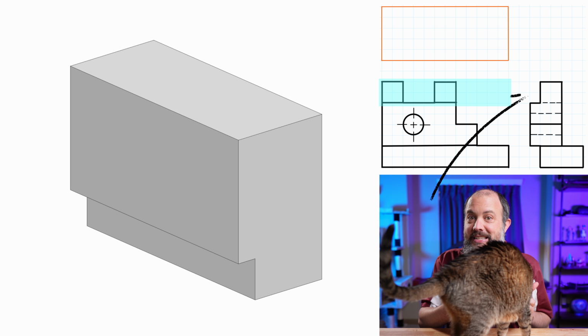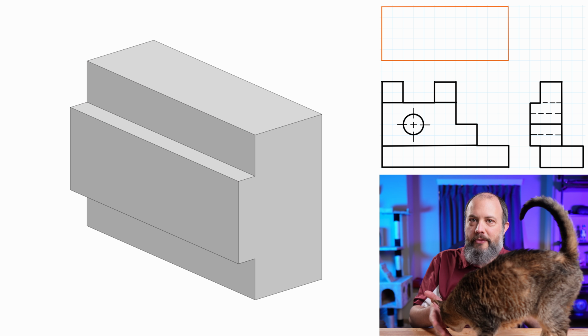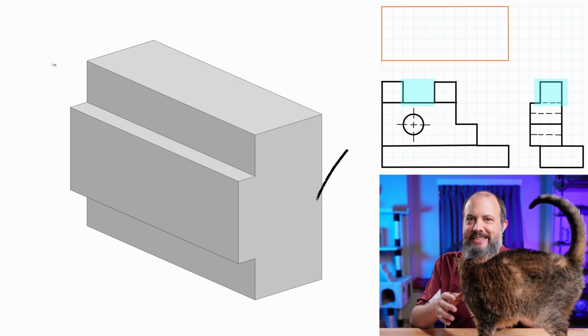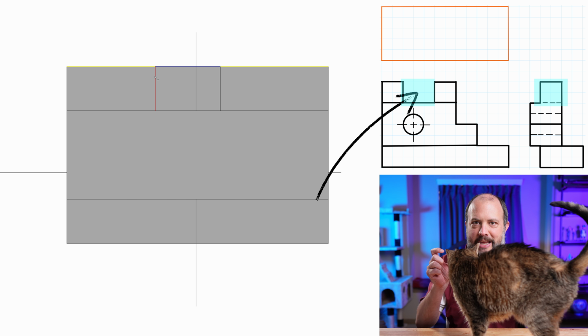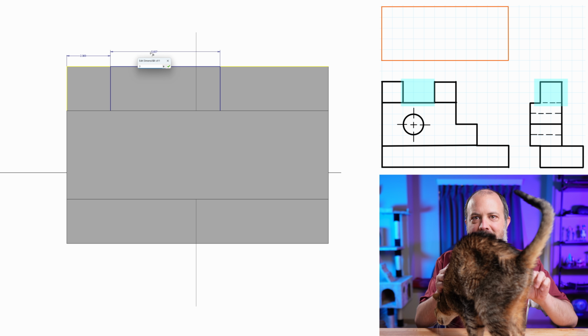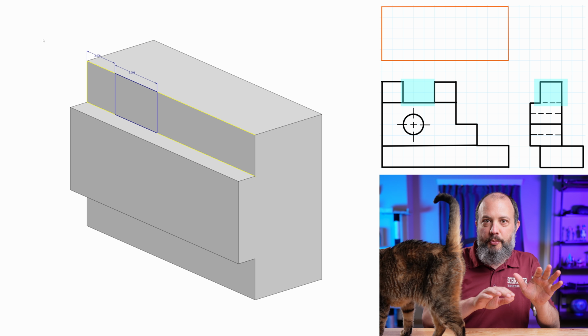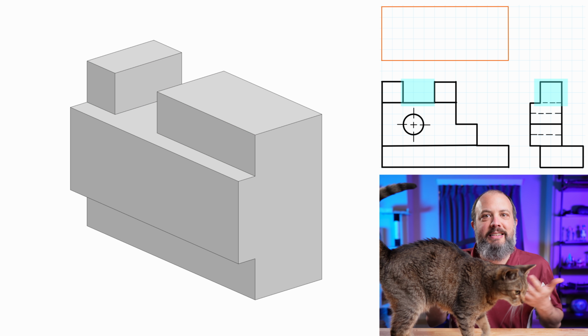Right above it, you can see that there's another rectangular cutout on the top half as well. Moving over to the front of the drawing, I can see on the top left, there's a box that's cut out between the two squares that remain. So on my 3D drawing, I can draw that rectangle that gets removed and extrude it into the shape to cut away that top material.